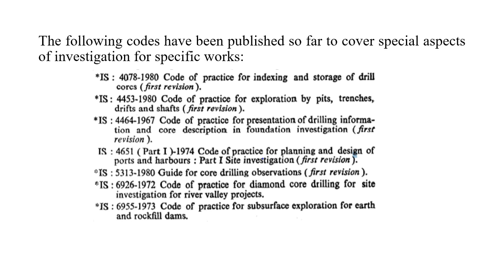So you have IS 4078-1980, which is a code of practice for indexing and storage of drill cores. Then there is IS 4453-1980, which is a code of practice for exploration by pits, trenches, drifts, and shafts. So likewise, there are various other IS codes available, which cover the various types of works coming under subsurface exploration, or which require subsurface exploration. Okay. But most frequently we will be following IS 1892-1979. Okay, you can keep that as a base reference.